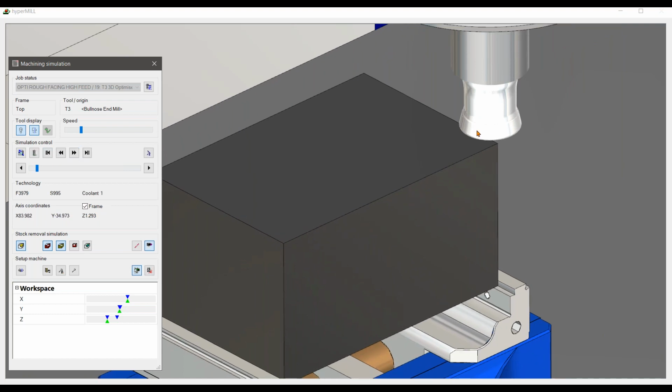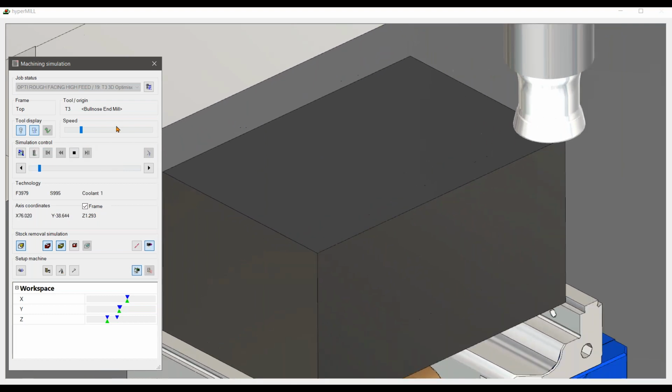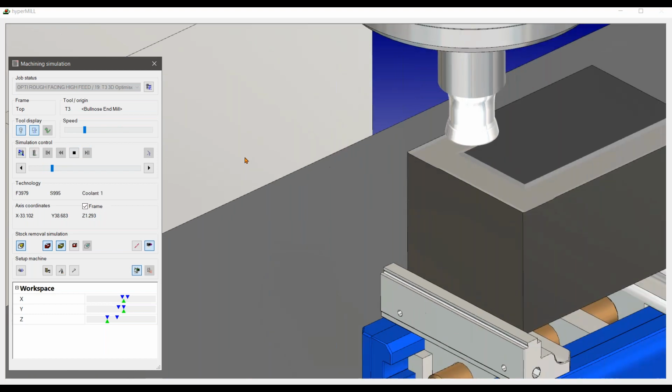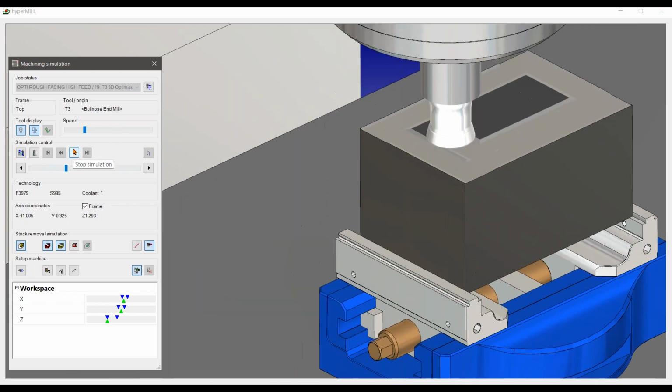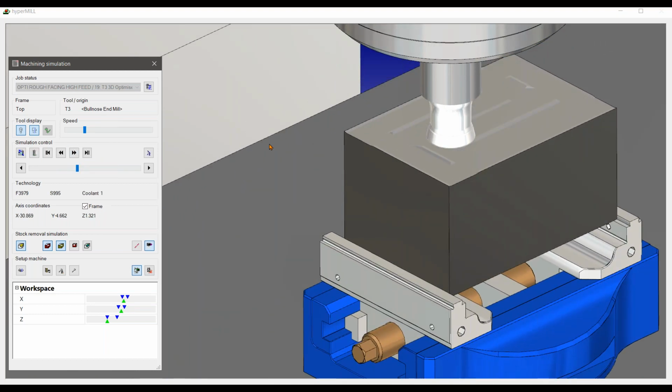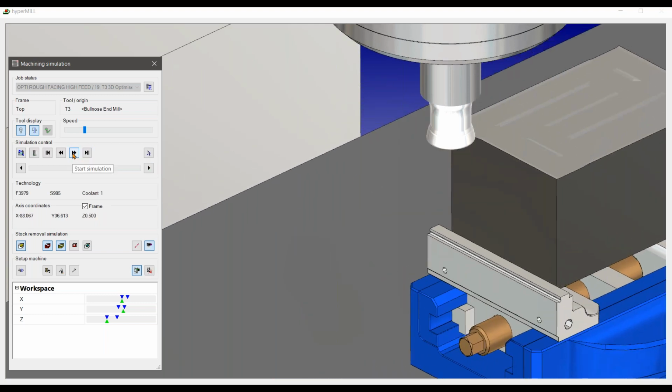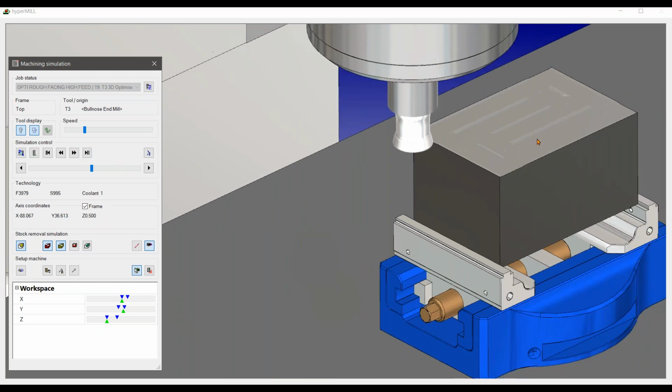First of all, I start the pass over here on the right-hand side. Once it's done its first pass, the tool is then retracting to the nearest start point. Again, I'm back into cutting material already. I'm not having to retract up to a safe position, back down to the start position it used first of all. It's adapting all the way down for the best result.